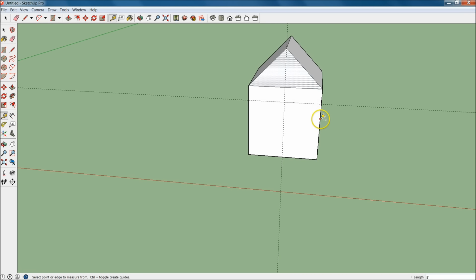Now we can do math here, and we can say, okay, we've got a 10-foot span right here. So if we want this to be 3 feet, the difference is going to be 7 feet. So we'd go 3.5 feet off each edge. But let's just make it easy on ourselves. We're going to bring this out to 1.5 feet. So I can actually do 1.5 feet, and that'll give us 18 inches. Boom, right there. Again, I can check right there with my pencil tool.